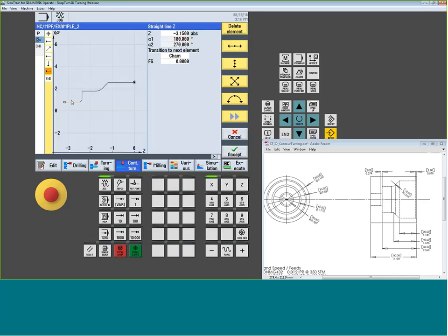Now, at this point, those of us that do a lot of OD work are used to doing a pull out to the rough stock, and you can do that here. The problem is, if I pull out to the rough stock, I'm now forcing the tool, even on the finish pass, to pull back and start moving the back of the boring bar towards the other side of that hole. That can get a little tight, especially if I have a big boring bar here. Typically in an ID, I will usually end in a Z move. Now what the system will do, because that's the last geometry point, it will overcut this position by the radius of the tool. It will position the tangency of the radius of the cutter, in our case 31 thou.